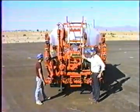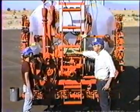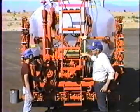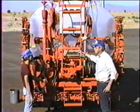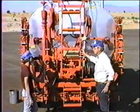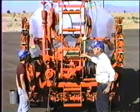Never leave the burner unattended. That is, if you're heating material, if you have that burner running, stay with the truck. You might be in the cab and get out and look at things once in a while, but be here. A lot of things will burn on this thing. Once you've used it a while, it's coated with asphalt, it's got diesel on it, and a lot of things catch on fire. You need to be here. If it catches on fire, at least you'll have a chance to say, I tried to put it out. If you're off someplace else and it burns down, then you can't even say you tried to put it out. So you're the thermostat.